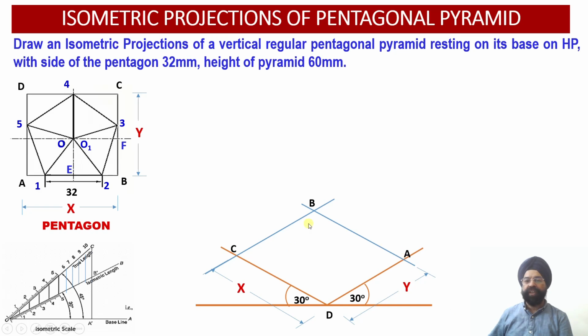Now you see, I have drawn this rectangle. Having drawn this rectangle, I am going to do two things. I will measure the true length of this distance AE, transfer it over here onto the true length, and work out the isometric length corresponding to this distance AE. This is again a straight line, or rectilinear, distance. So from A, I will mark point E over here. Again a center line will be drawn. Similarly, from point B, I will measure the distance of point F.